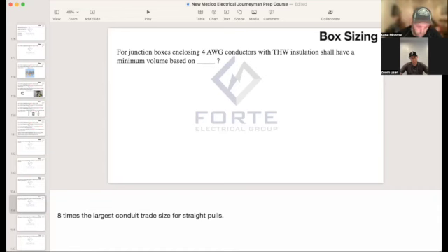So you just do your square footage, which comes out to 40 times 23 times 3, which is 2,760, and then you multiply that times 3 VA because you're on a single family dwelling. That's 8,280.